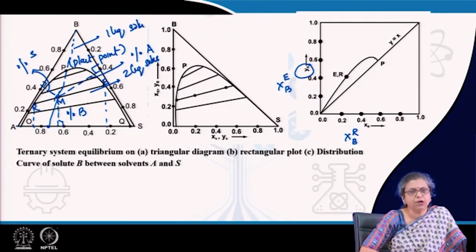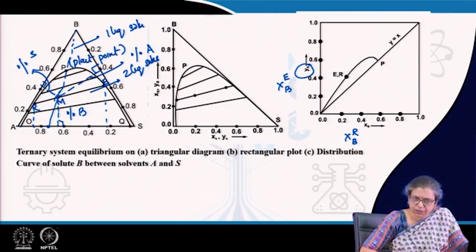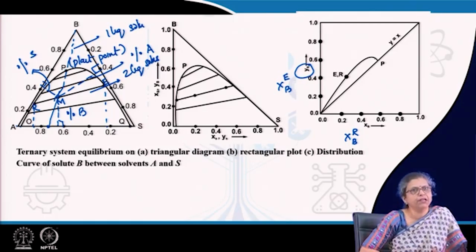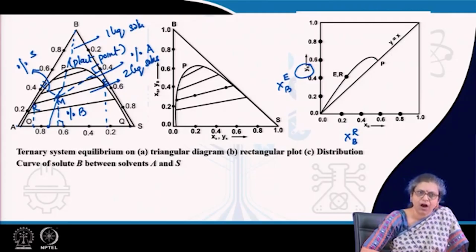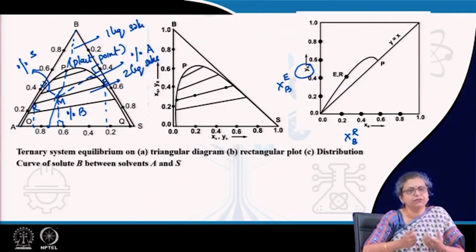Based on that we can express the equilibrium data either in terms of plots or in terms of K. The K values are usually used for ideal solutions, and they are very frequently used in hydrocarbon industries, because mostly those solutions are hydrocarbons, which form the members of a homologous series. So, they form ideal solutions. Very frequently they are expressed in terms of alpha, which gives you the relative ease of separation.